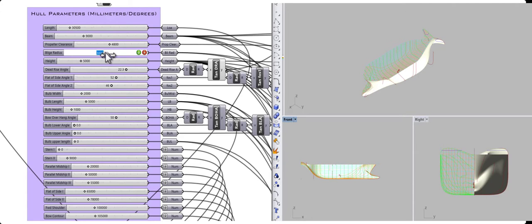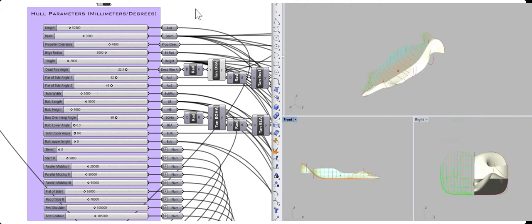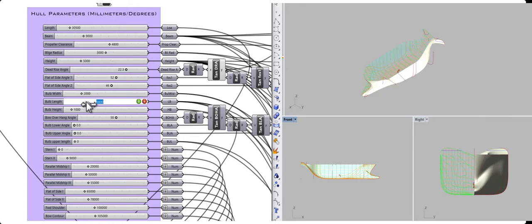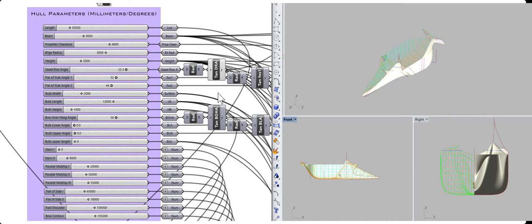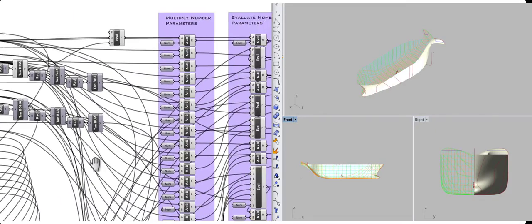Some of the parameters are fed into a number battery that has a division expression computed within it. This allows these particular parameters to subtract from the resulting point in space. The points that are being constructed are then fed into the V input of a NURBS curve battery. This allows a continuous closed NURBS curve to be constructed out of the vertices of each point in space.